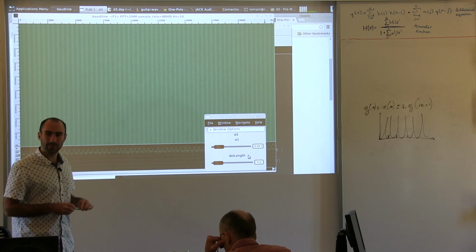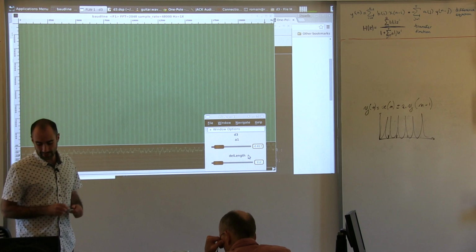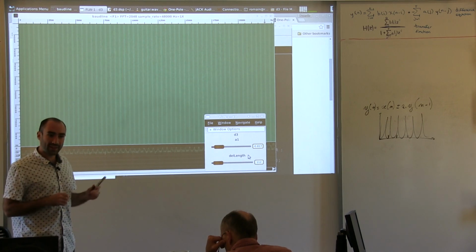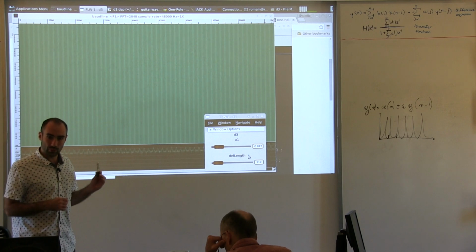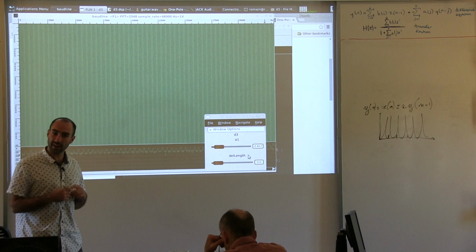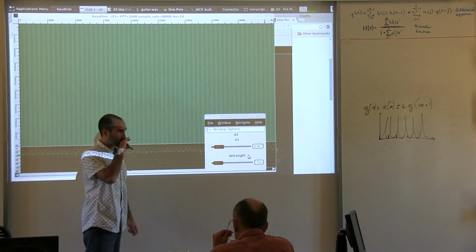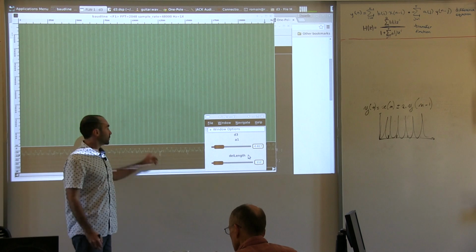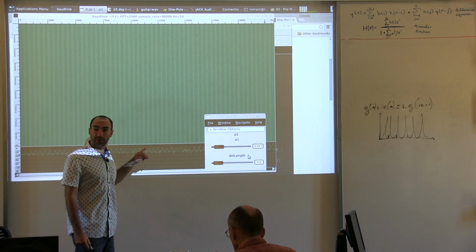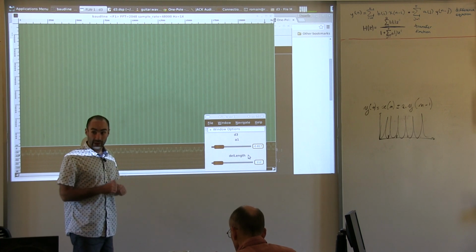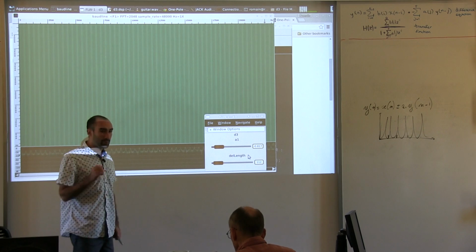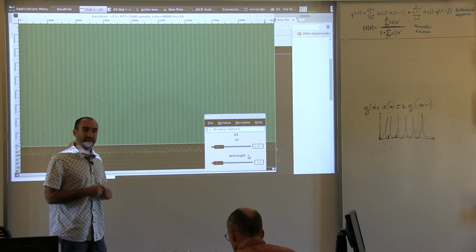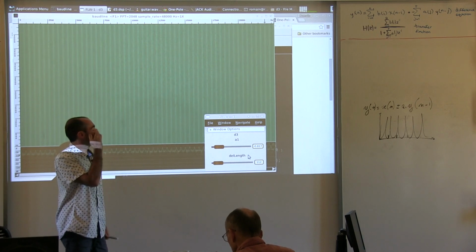So maybe before we do that, because I feel like it's after lunch, you guys are probably a little bit tired, your brain is probably very slow. Our next exercise after this one will be to modify the flanger that we had yesterday, so that instead of using a one-zero filter to do the flanging, it will be done by the one-pole filter. And then it will be a real flanger. It will be way more effective than the one we were using yesterday. So that will probably be the next exercise that we'll do later.